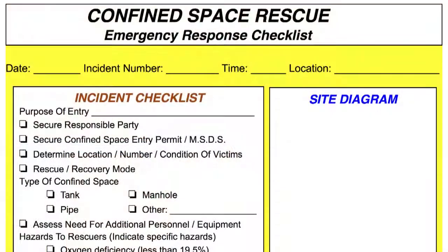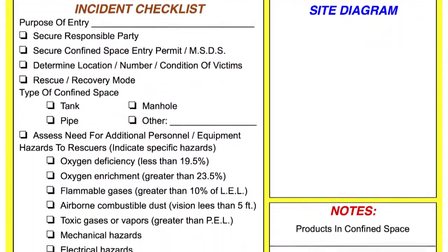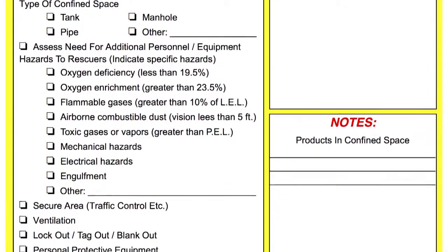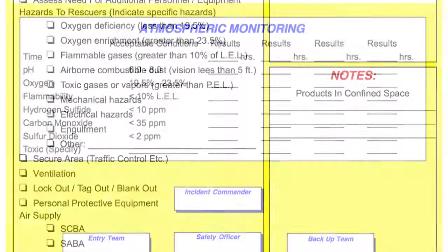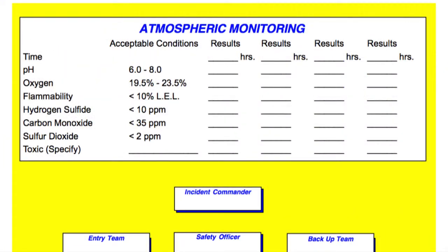As we approach the confined space or the trench that potentially has a compromised atmosphere in it, we're monitoring our readings and we're making sure that we're evaluating and documenting immediately what those readings are. One of the imperative components of atmospheric monitoring is documentation. So you want to make sure that you keep a log of all of your readings and that all of your samples, which are done continuously, are being recorded on a 5 to 10 minute basis.